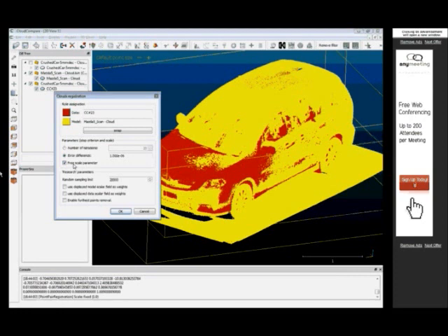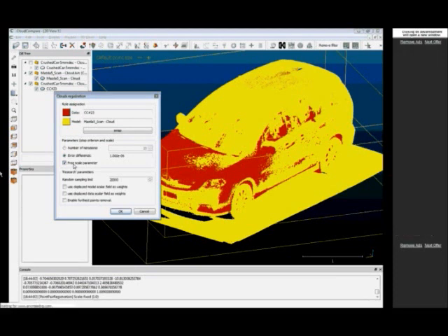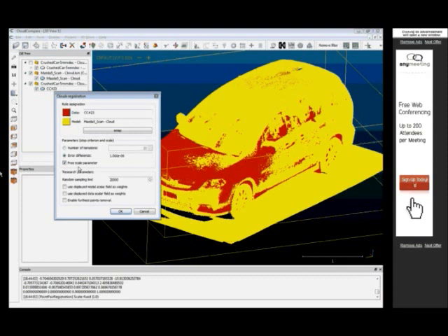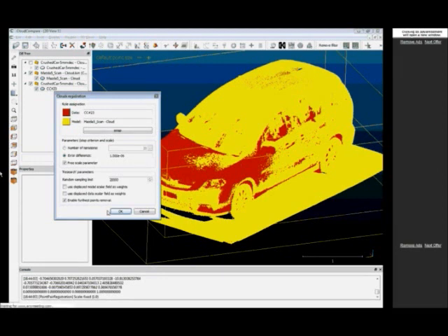And we'll also enable this option, which is enable farthest point removal, and which is basically a way to tell CloudCompare to ignore the farthest points at each iteration more and more, so that the bigger differences don't interfere with the registration process, and it lets the ICP process converge much better.